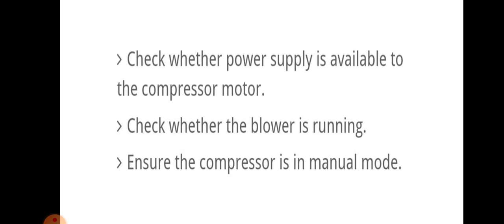We have to check whether power supply is available to the compressor motor. Check whether the blower is running. We have to ensure the compressor is in manual mode.